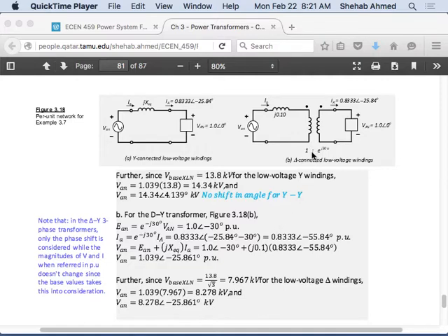Right? Why? Because this is in per unit. The 1 to n high voltage over n low voltage square root of 3 e to the j30 is the case of not per unit calculation. Right? Actual values calculation, if you're calculating the circuit in actual values. If you're calculating in per unit, it's only 1 e to the j30. Where is e to the j30? You put it on the star side, the high voltage side. That's the standard. The standard says the high voltage side will lead by 30 degrees. So you automatically put 1 e to the j30.